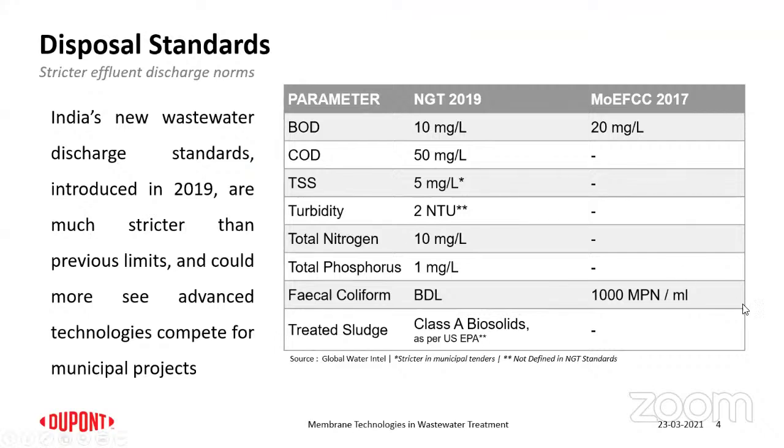So nutrients like nitrogen and phosphorus have also been reduced. Earlier, there was an allowed level of fecal coliform that could be dumped because the biological entities in the water, like fishes and others, could also bring them down. But again, it was made to below detection level because there is already enough food for the flora and fauna in water. So it is our duty to bring them much lower. So all these have actually pushed membrane technologies to be employed in wastewater treatment.